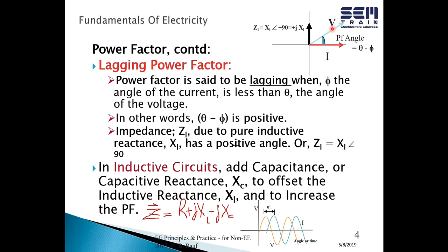Well, now let's assume that the inductive load that was causing the current to lag behind the voltage is turned off, shut off, taken out of the system, whether temporarily or permanently, doesn't matter. When the inductance that was causing the current to fall behind the voltage disappears, that's as if you've overdosed the system with the equivalent amount of capacitive reactance. So what will theoretically happen is that the current will go past the voltage by 30 degrees.